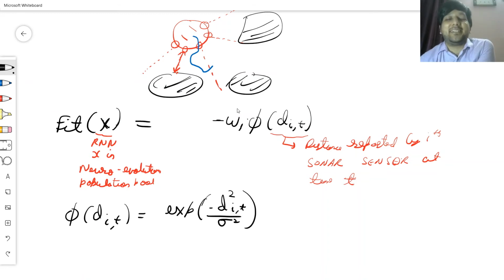So, I tell the objective function exactly that. I need to maximize the linear speed. So, let's say W2 times this thing. Otherwise, my robot will learn that it should never move when it's away from the obstacle because this thing is the smallest. So let's put a summation over time over here.